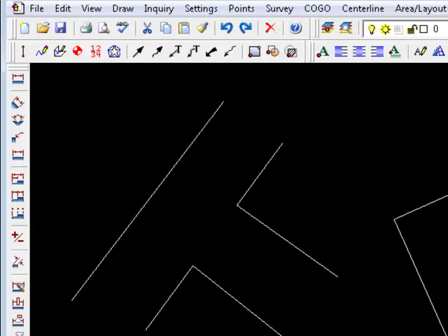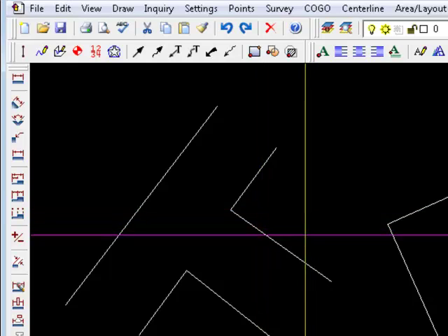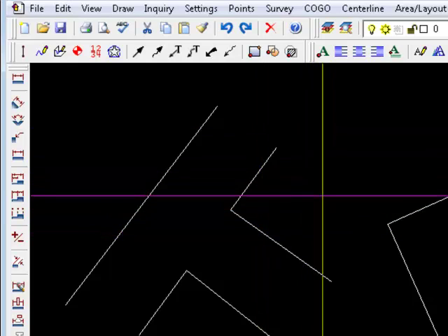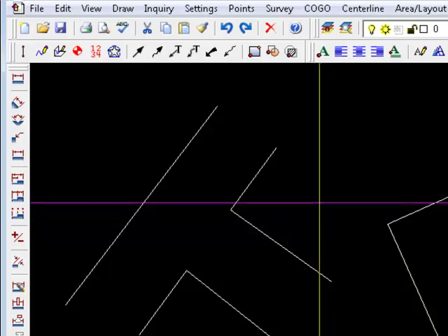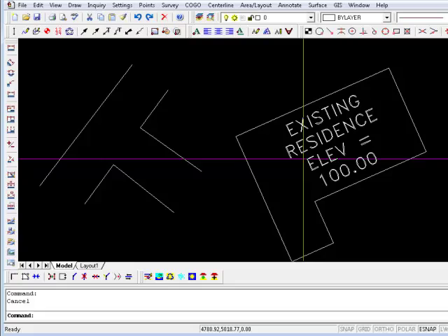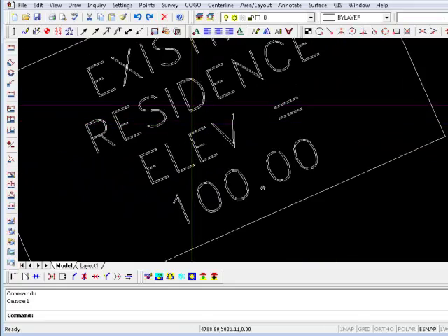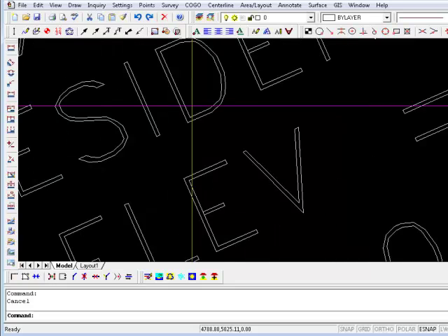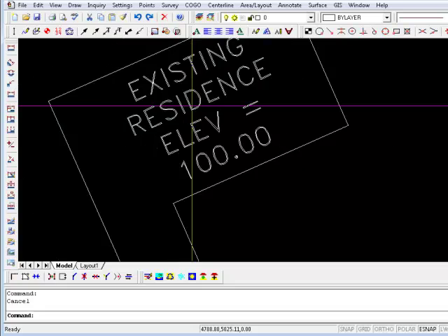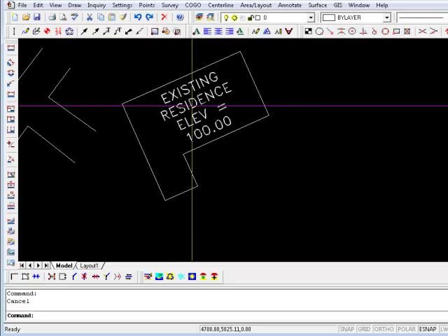Zoom is the next thing we want to talk about. If you have a 3-button mouse, and the third button being the wheel, zoom is very easy. You use the wheel to zoom in. You'll rotate the wheel one direction and zoom out by rotating it in the other.